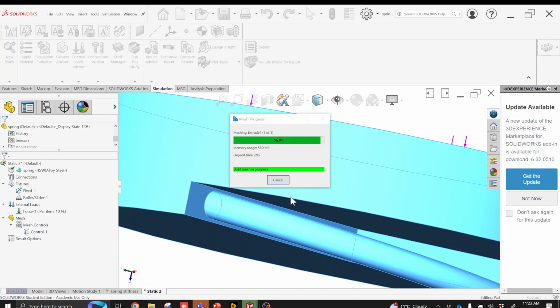So it's going in the background, it's looking at all the surfaces that are there, it's discretizing the geometry, and maybe in this case, live in the lecture, it probably makes sense to make it a coarser mesh, because if it takes this long to mesh, it's probably going to take a lot longer to solve. So we'll see what happens here in a second. I think on the coarse setting it took like 5 seconds to mesh, so it's almost an order